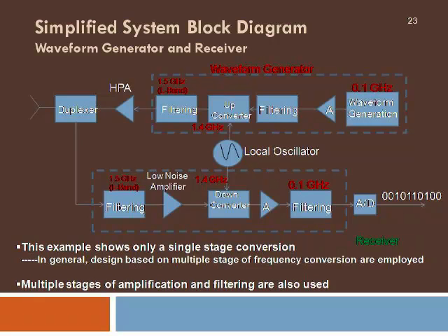The waveform generator is going to be a simple oscillator, maybe CW or a pulsed one. Then it's going to be amplified, then filtered properly to see that it satisfies all the requirements for the up converter. The same local oscillator can be used in the transmitter as well as in the receiver blocks. So using a 1.4 GHz local oscillator, you can mix this low frequency signal of 100 MHz to 1.5 GHz by using a frequency selective filter.